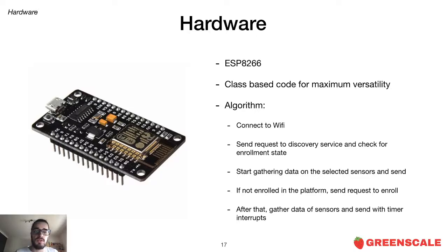The hardware development was done through a NodeMCU development board that contains an ESP8266 microcontroller from Espressif with Wi-Fi capabilities. In the current state of the MCU, it connects to the Wi-Fi, enrolls in the Discover database, measures the data and sends the measurements to the server. The future full-fledged production-ready NodeMCU should be done in a different way, maybe using a PlatformIO Python pipeline build to enroll the sensors when the microcontroller is programmed. This makes it possible to know which microcontrollers are legit. Due to time constraints, it was hard to properly develop efficient code to support this.